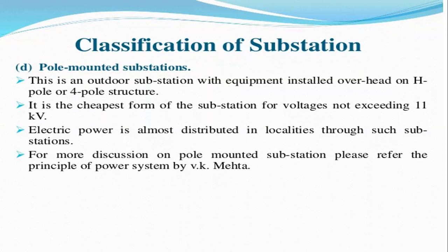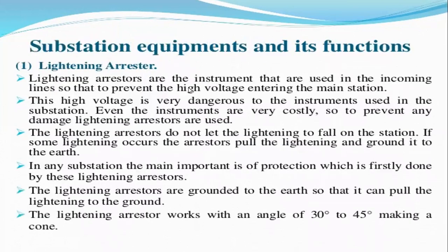Okay, it is only suitable for distributing the power to the local areas. Very high capacity substations cannot be installed on the pole. Only up to below 11 kilovolts can be installed. Okay, these are the various types or classifications of substations.